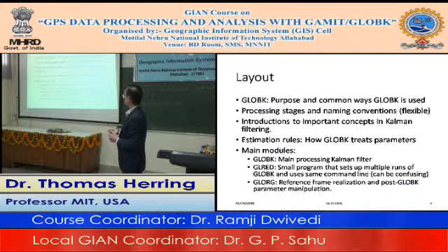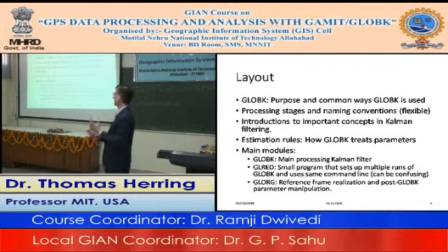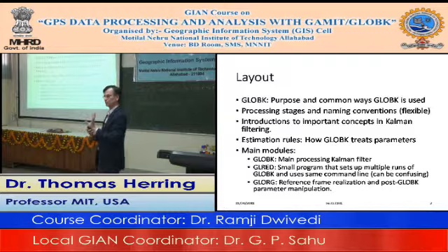And then there is GeoLog, which is the reference frame realization and post-GLOBK estimation process. GeoLog is built into GLOBK itself, but it also can be run as its own separate program. In fact, GLOBK has that characteristic that its main modules are separate programs that are all blended in the one program. So most of the things you can do in GLOBK, you can actually run a separate program to do if you wish to.